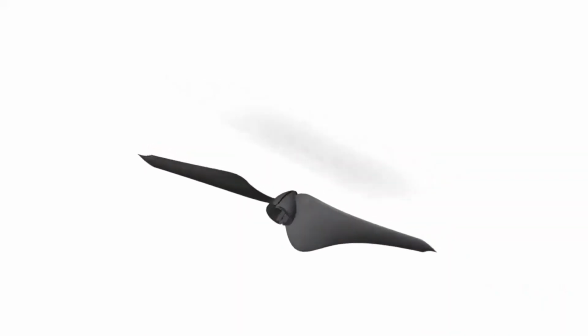Since we wanted to make the hub as large as possible, the turbine needs to be foldable during the printing process to satisfy the requirement of being printed as a single part. As such, a hinge mechanism was designed. The placement of the hinge needed to be on the hub, as hinges on the blade would disrupt the airflow.